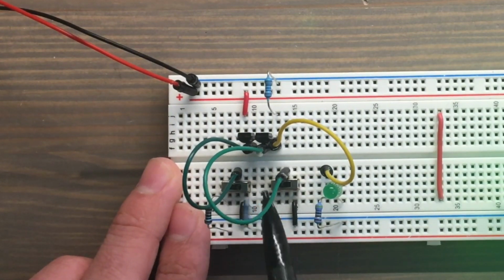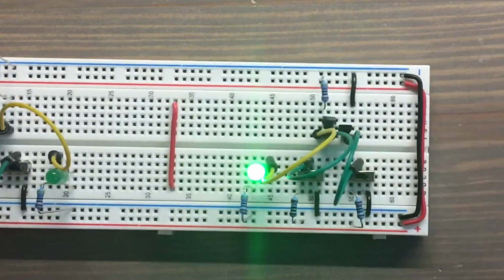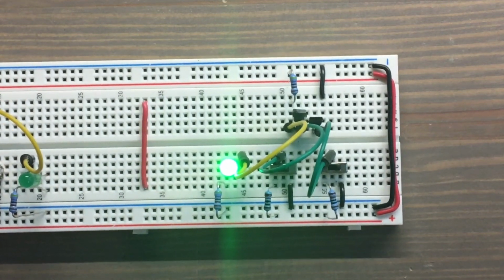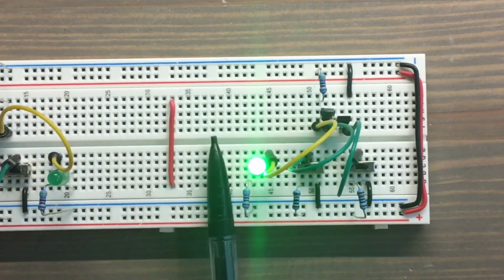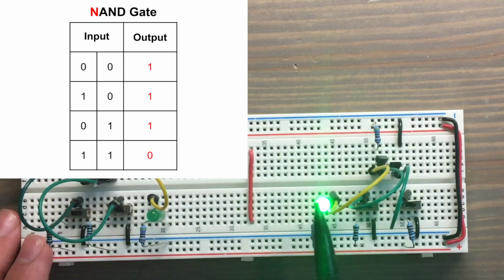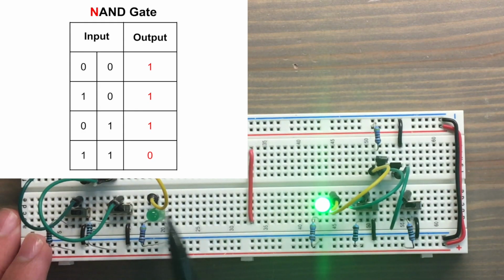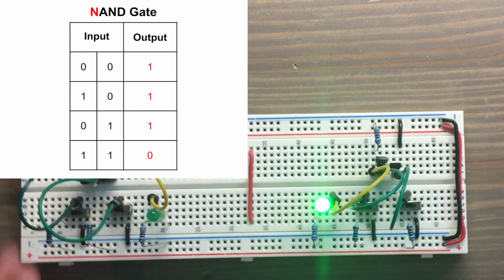Okay, now over here on this other side we have our NAND gate. So there's in total 7 gates. We have the NOT gate, the AND gate, the NAND gate, the OR gate, the NOR gate, the XOR gate, and the XNOR gate. And other than the NOT gate, they're all in pairs of 2. For example, the AND gate and the NAND gate. And basically what a NAND gate is, is just the output is inverted from an AND gate.